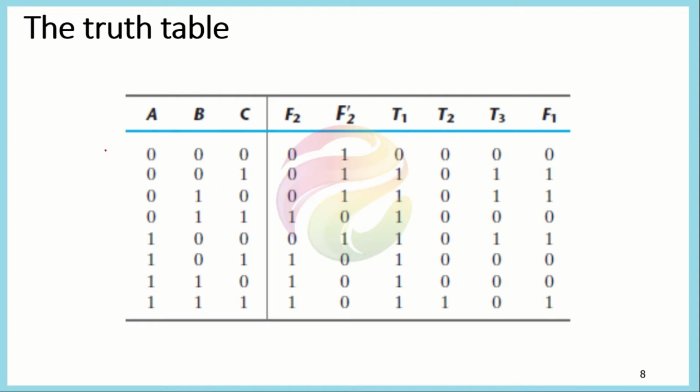A better way to understand this is to draw a truth table. Because from the truth table we can judge quite appropriately what the main functionality of any given function is. Because there are three inputs involved, A, B, C, first we need to write all the combinations of the three input system. So we have written the 8 combinations here.